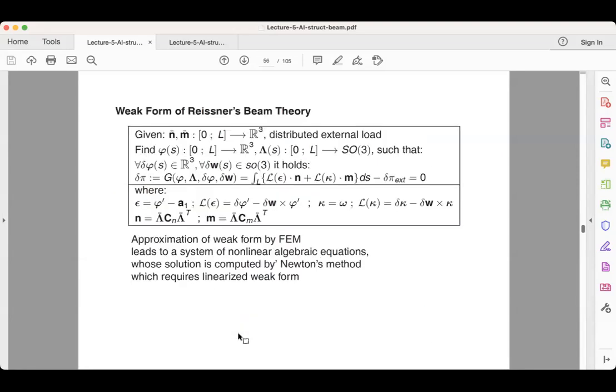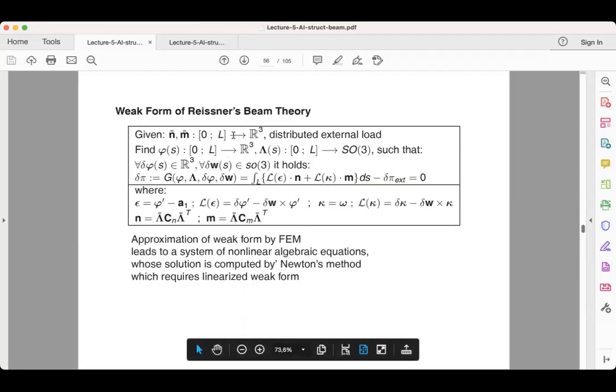I don't remember if I've done it here, but in any case, this is the kind of thing that is done there. It's really the same thing we've already done for large displacement, but now it has to be adapted to the stress resultants. And it turns out that because you have the second Piola-Kirchhoff stress by pulling it to the initial configuration, in the weak form you have a Biot stress, because from the initial to the deformed configuration is just a rotation, which is the hypothesis of this structure.